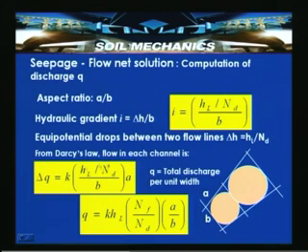From Darcy's law, if you again apply, then we said that Q is equal to K into HL, where HL is the total head loss which is occurring, into NF by ND, that is the number of flow channels to the number of potential drops, into A by B, which is nothing but the aspect ratio. We said that while constructing the curvilinear squares, this aspect ratio is maintained as 1. So, let us look into a problem.